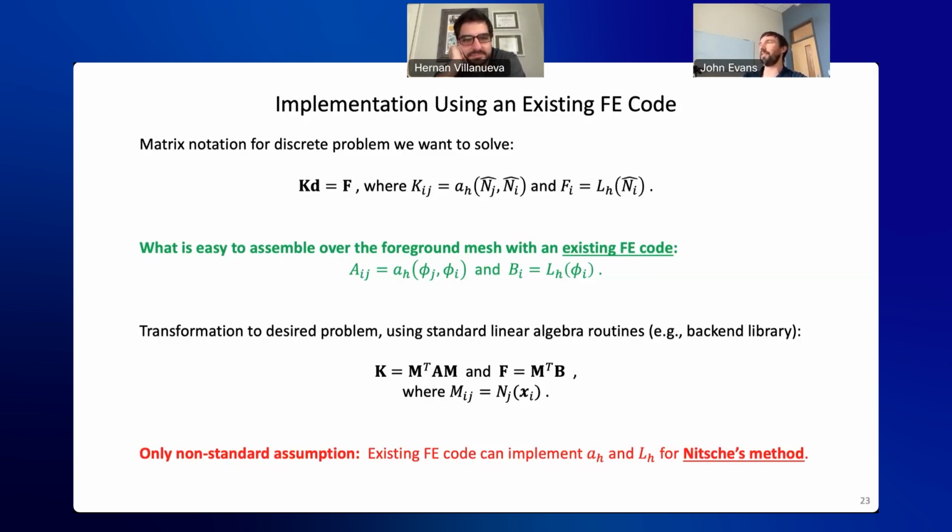There's many different ways of doing that process. STL, fortunately, you can think of it as just being a truly linear representation of geometry. So you can create an implicit representation, an exact implicit representation, much, much more easily than for a B-rep.